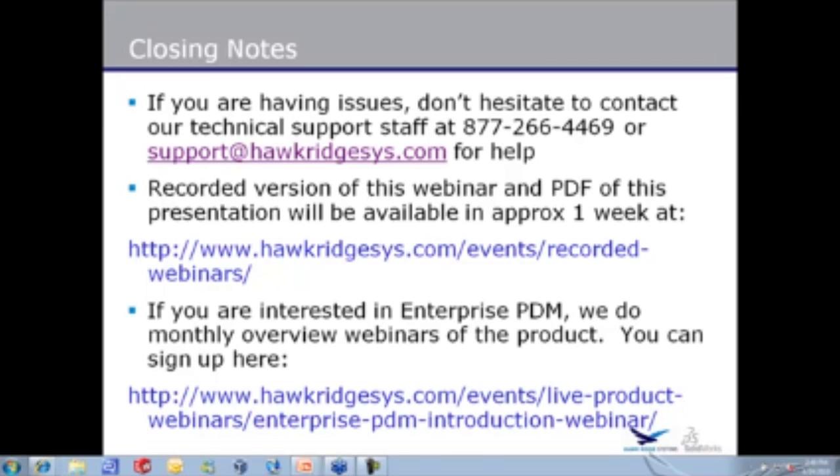Question, do we have to stop the service to clear the log file? You should. You don't absolutely have to, but if you're going to browse into the Vault data folder and do anything, clear the log file, restore deleted files, anything that requires you physically changing something in the Vault data folder, you should definitely stop the service. You shouldn't just be randomly browsing in there and changing things. That's going to definitely cause problems.